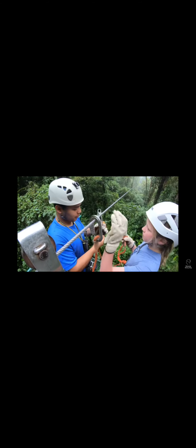So yeah, snatch blocks can get you out of a hairy situation. Knowing how to use them can help you make friends, and they can also be a ton of fun. Zip lines are basically just snatch blocks. You have the ability to break apart the pulley, and you can insert a cable into it without having to disconnect the cable from either end. That's essentially the definition of a snatch block, a pulley where you can insert a line without having to take apart your line from whatever it's hooked to.